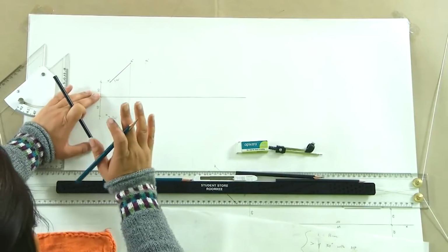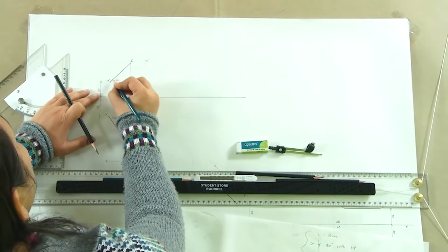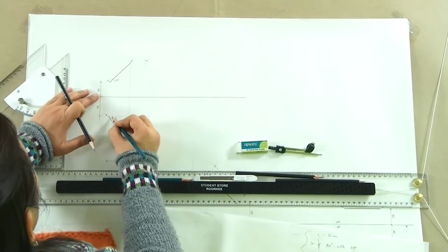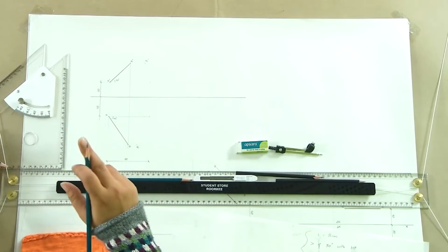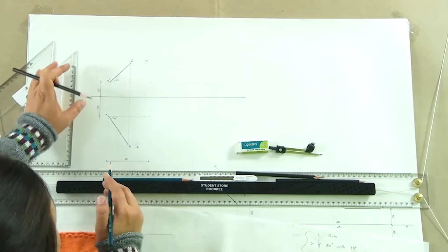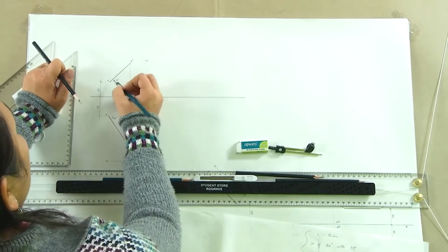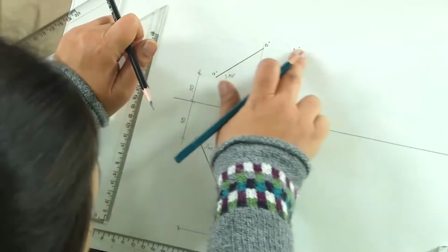In that case, what we would be given is what is the trace. So, we might be given the horizontal trace and the vertical trace of the line which is inclined at certain angle, and in addition to that, we might be given the angles that the projections make. In that case, the same process will be done, but in a reverse manner. So, what we would do here is, we will draw the traces at the given angles, say alpha and beta, and then draw the locus of it.